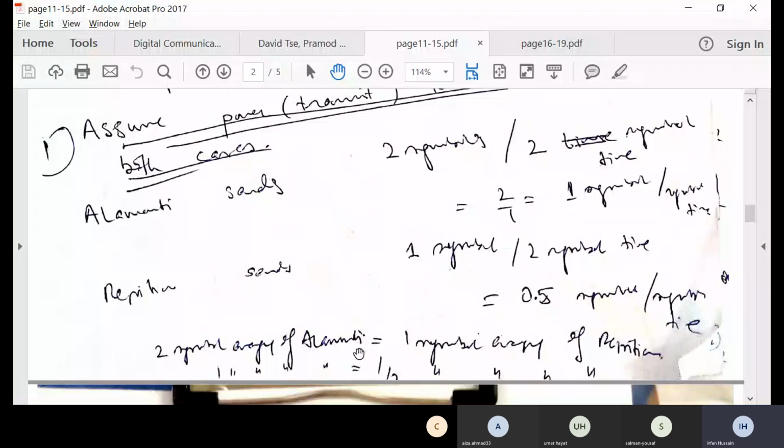So in the second case, let us say that these two symbols on which LMOT works are BPSK symbols. All right. You know BPSK symbol is minus A, plus A. So with only two symbols, you just require one bit for representation. So if you are sending two symbols, you just require 2 bits. So if I use BPSK for LMOT, it will be using 2 bits over 2 symbol times.